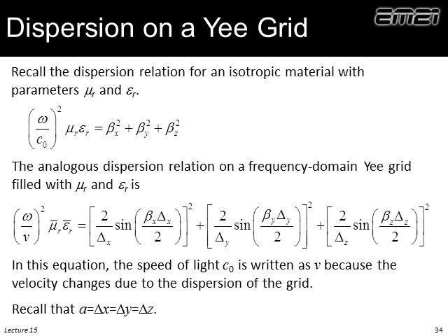We're not quite there. We know from last semester there's numerical dispersion on a Yee grid. In other words, even if we set our grid to all free space, just due to the interaction of the numerics, our wave is traveling slightly slower through our Yee grid than it would in real life. So that means the average material properties, which we think might be our effective material properties, are slightly too large. And we go back and we borrow what we discussed last semester for compensating for grid dispersion to adjust those material properties so we get the actual effective material properties of that unit cell.